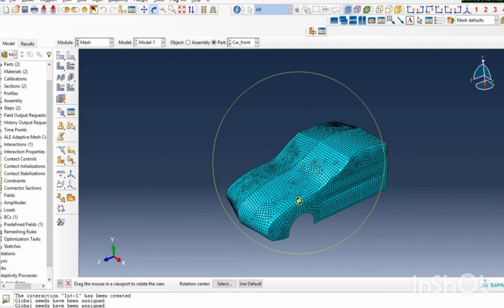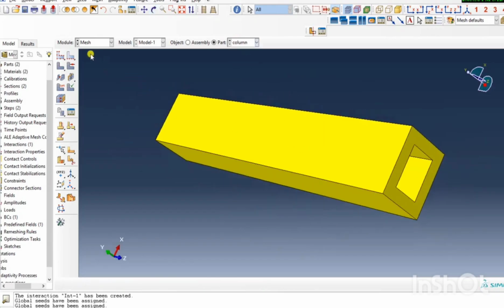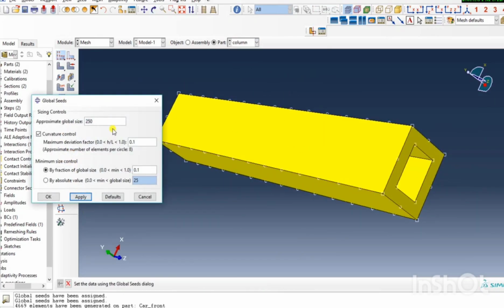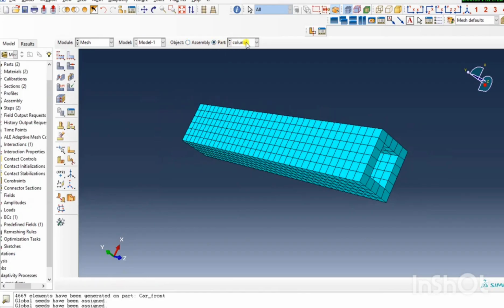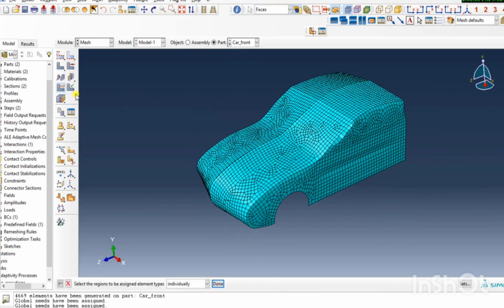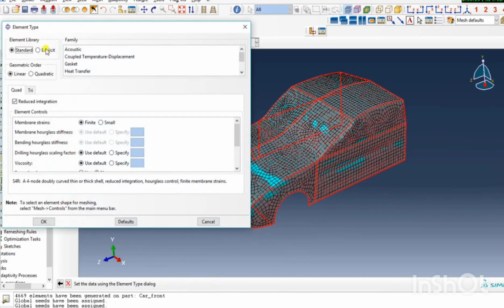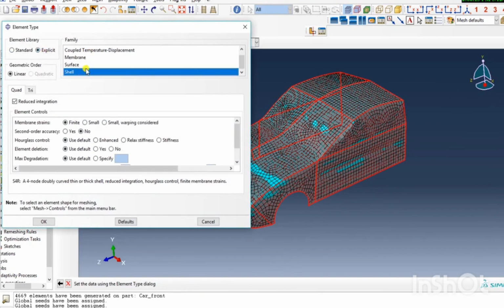Typically, steel properties include a Young's modulus of approximately 210 gigapascals and a yield strength in the range of 220 megapascals, with the plastic deformation governing the energy absorption during impact, as already described in the Abaqus documentation if you are able to get it. Otherwise, I will just put it in the description of this video.